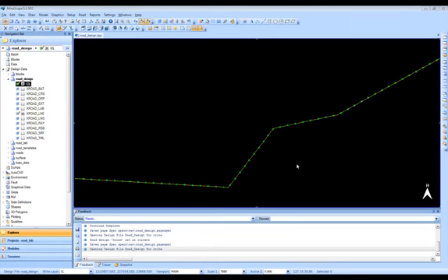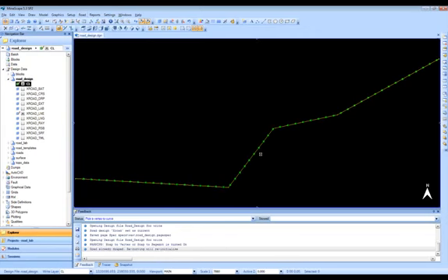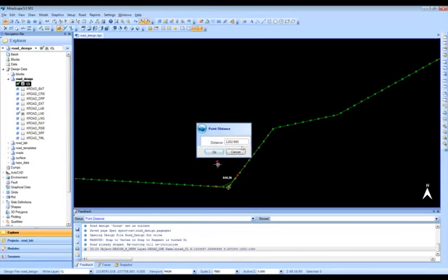Okay, now that I have my initial center line defined, the next task on the list is horizontal alignment. Here I'm going to enter a curve into my alignment. I'm going to have a curve down through here, horizontal. So I'm going to pick this corner, and I'm going to enter in a curve. And you can see the transitional curve coming in on that as well, with those two markers there. And this is pretty dynamic. You can see the radius change, but I'm going to enter a specific radius of 1200.